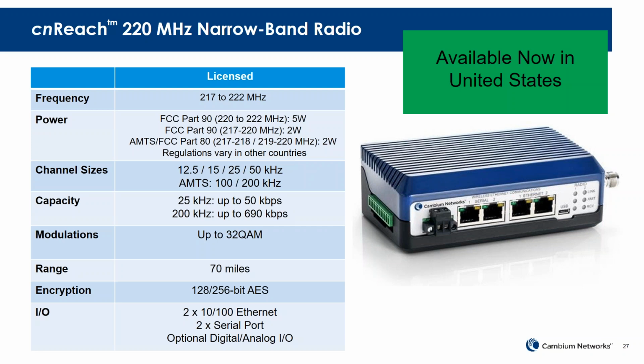The other variation to consider is that the radio does adaptive modulation. So if there is some interference or propagation that causes the link budget to force the radio into a lower modulation, that will happen automatically, and you'll see that speed vary with the conditions of the link, based on the hitless adaptive modulation algorithm.